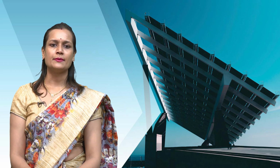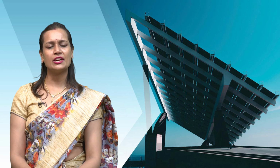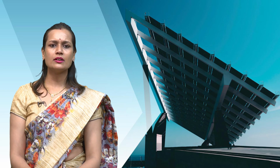When designing and sizing a solar energy system, reliable solar data is required. The most relevant data is the average daily radiation, that is the total solar energy received per day per meter square on a horizontal surface. Global radiation consists of the direct sun radiation and diffuse radiation of the sky. The strength of the radiation of the sun depends highly on the location of the earth and is directly dependent on the hour of the day.